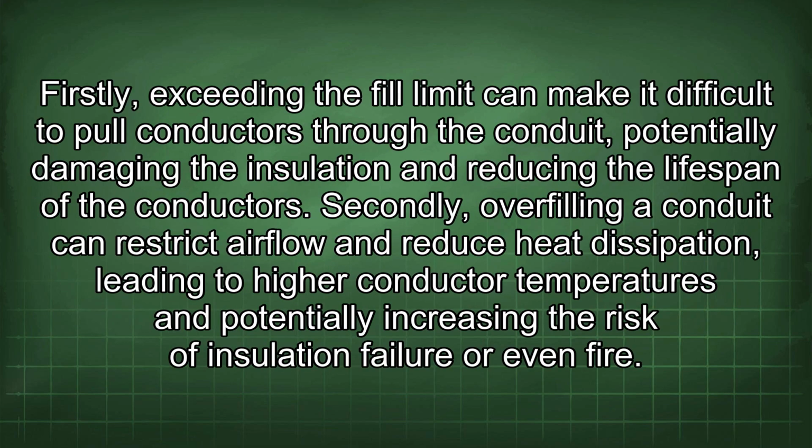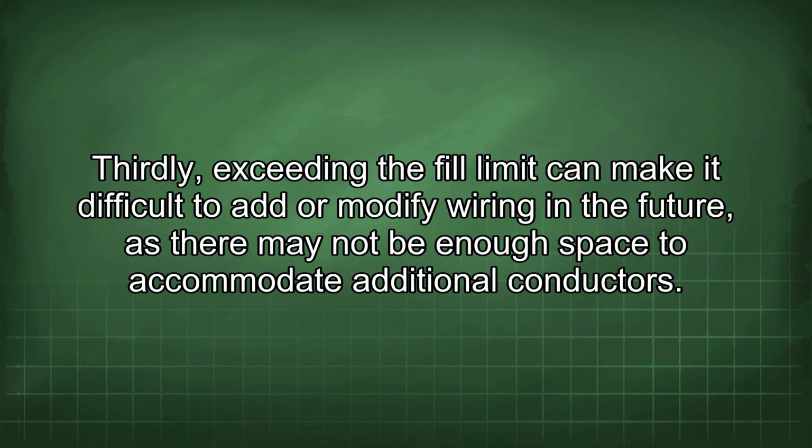Firstly, exceeding the fill limit can make it difficult to pull conductors through the conduit, potentially damaging the insulation and reducing the lifespan of the conductors. Secondly, overfilling a conduit can restrict airflow and reduce heat dissipation, leading to higher conductor temperatures and potentially increasing the risk of insulation failure or even fire. Thirdly, exceeding the fill limit can make it difficult to add or modify wiring in the future, as there may not be enough space to accommodate additional conductors.